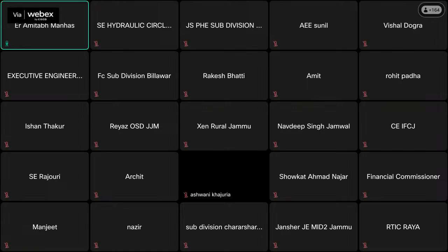As I told in the last slide, if the floor area is less with us, we can go for vertical turbine pump. If the net positive suction head available is also less, we can go for vertical turbine pump.